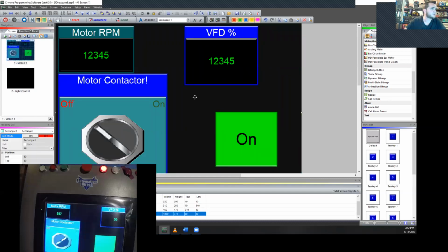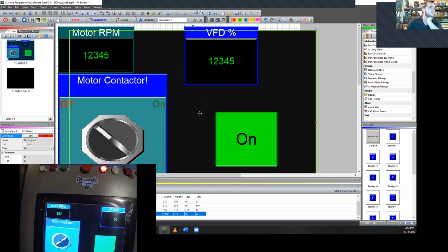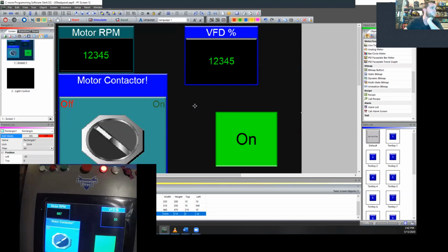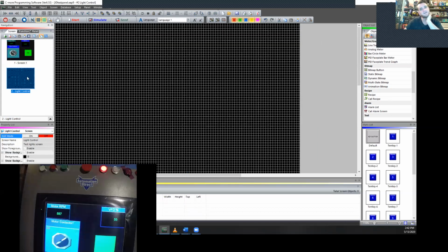Oh, I know why it's so ugly. Forgot about that. Okay, so I forgot on this screen, instead of changing the background color, I just added a big black box behind it to wash it out. So you can see here, the benefit to not doing that is these grid lines actually show you the touchscreen nodes. Every intersection point on there is actually a point that it's sensitive to touch. And that can be important if you're trying to shrink a bunch of small stuff on there, just seeing where any overlap might be between buttons and stuff. So, okay, we have these two screens.